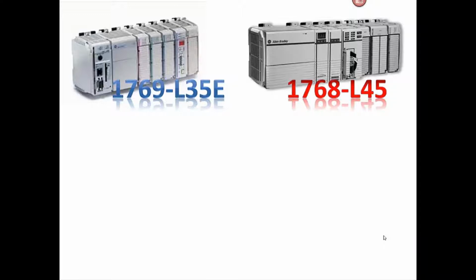On the right you have a power supply, then you have an Ethernet bridge. There's a difference between an Ethernet port and an Ethernet bridge. And you see right at the bottom of the face it says EtherNet/IP. And then you have a SERCOS card, which is for motion control. It's a fiber optic interface between the backplane of the L45 and Kinetix or Ultra type SERCOS motion drives.